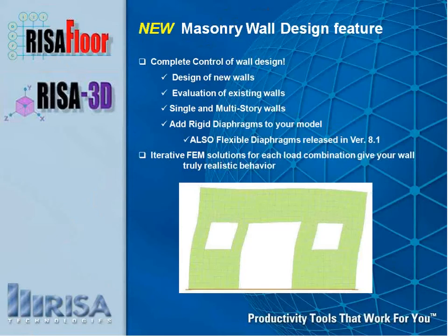We also have an iterative FEM model behind the scenes. So when we're looking at this screen, we see that there's an actual submesh of plates happening underneath that wall. And what that gives you is the power to get the truly realistic behavior of how that wall is deflecting and what its real stiffness is based on its geometry. That right there will be one of the best things that we see as we develop this full model. We'll be able to work with that FEM model automatically, so no more drawing in your plates yourself.